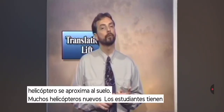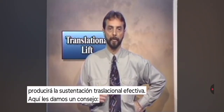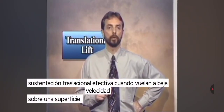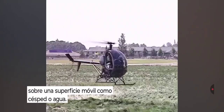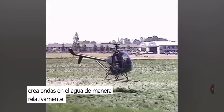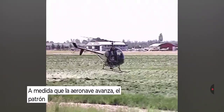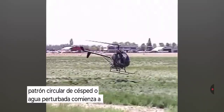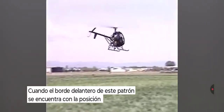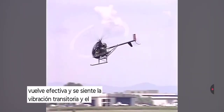Many new helicopter students have trouble judging when effective translational lift is going to occur. Here's a tip for you. You can anticipate effective translational lift when in low-speed flight over a movable surface, such as grass or water. The rotor downwash disturbs the grass or creates ripples in the water in a relatively evenly distributed pattern around the helicopter. As the aircraft moves forward, the circular pattern of disturbed grass or water begins to move aft. When the forward edge of this pattern comes abeam the approximate position of the rotor mast, translational lift will become effective and you'll feel the transient vibration and pitch up.